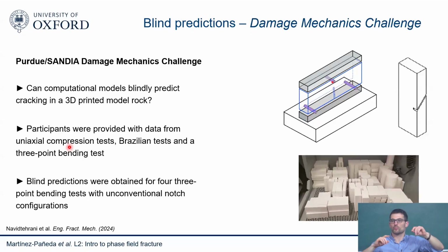We're going to see how the crack grows in 2D, but we're also going to do XCT scans, and we're going to record force displacement results. They said, we give you all of this, you need to tell us the outcome. And of course, we don't have the luxury of calibration. We don't see the results. We send them our calculations based on this data and the geometry of the test, the blind test, where we don't know the outcome. They send us the geometry, we reproduce it on our computer, we send it, and when all the teams have sent their calculations, they plot the final results and you see how close your model was. This is what they call a round robin blind test.